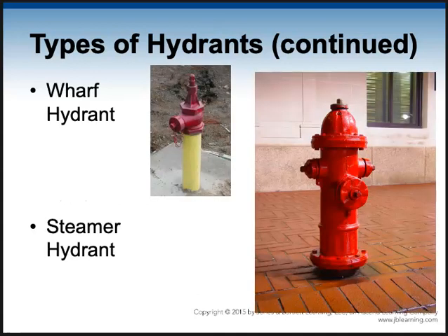So here's the 2 most common hydrants you're going to see are wharfs and steamers. A wharf hydrant is a single outlet, 2.5-inch hydrant. That one happens to be a dry barrel hydrant because notice that the nut is on top. If the nut is on top, it's dry barrel. So both of these pictures are dry barrel hydrants. The one on the right we would call a steamer hydrant. It's got multiple outlets, but it's also dry barrel.